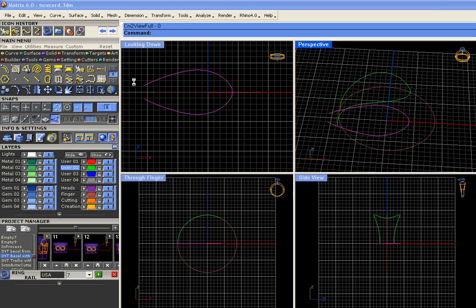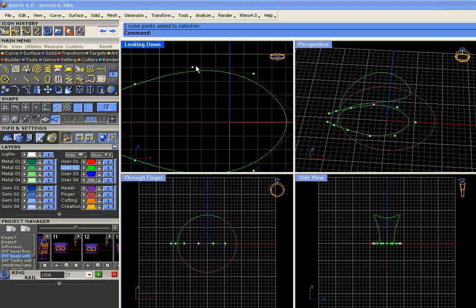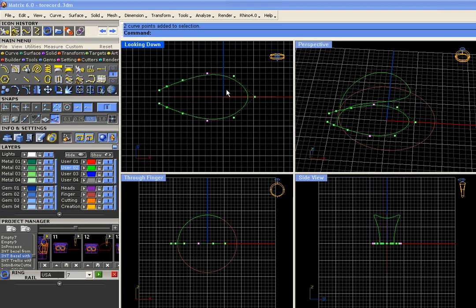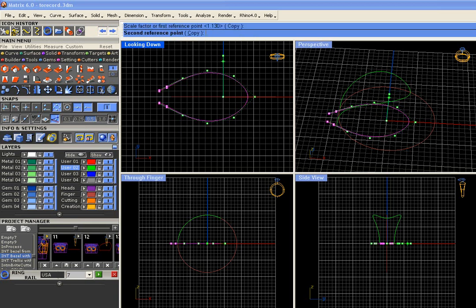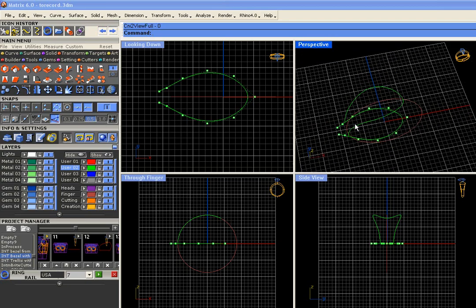And that way we can continue editing the control points, and it'll be a lot easier to do this because they're farther apart. There's fewer of them, so it's going to make for a more natural editing here. So just play with this. And I'm going to just go ahead and I'm scaling these from F4, pushing them inward or outward depending on the shape I want. F4, or scale 1D, F4, and just moving them around until I like the results.